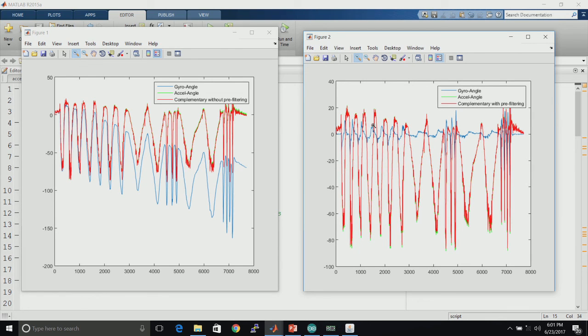After computing the angles, we see that we are trusting the accelerometer more than the gyroscope, but we can play around with the alpha value of the complementary filter to trust either the accelerometer or the gyroscope. We would trust the gyroscope more in a fast dynamic movement. As an example, on the left side we can see that till sample number 3000 we have a slow speed motion where we do not move very rapidly. We have a value which we compute in a very slow manner.